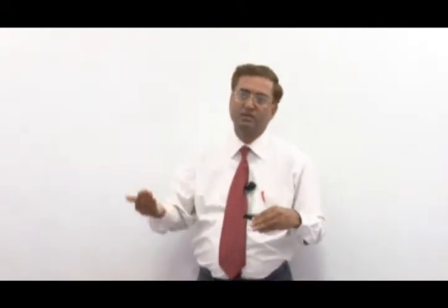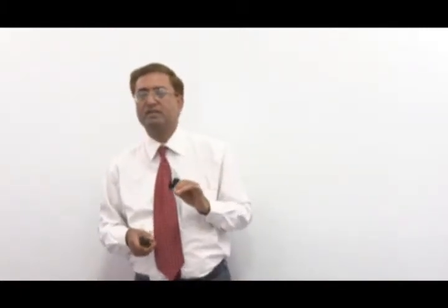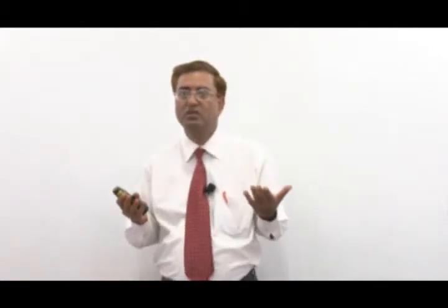So, if the stress on one side is sigma x, the other side, which opposes the deformation, has sigma x plus d sigma x, and that is how the deformation takes place. This is the force equilibrium on this small element dx. So, in the x direction the sum of all the forces must be 0.